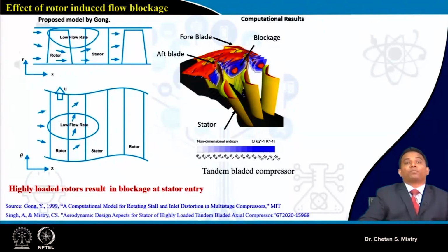You can say that flow leakage is happening twice. Because of the presence of this twice leakage flow, you can understand I will have low momentum fluid, or we can say a vortex, coming out. It will strike my stator, and that makes the design of this stator very challenging.